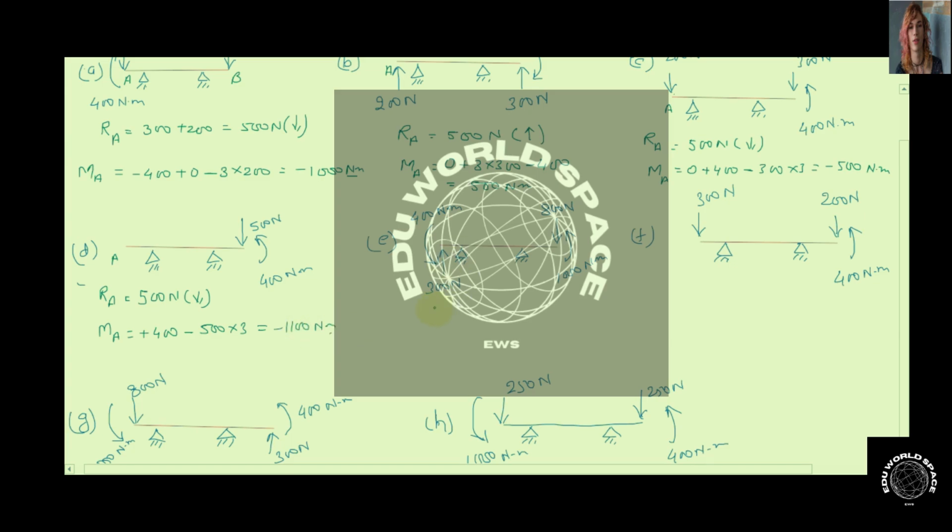Now if we talk about this case here, the reaction force at point A will be, since this 300 is acting upward, let's consider the upward direction to be negative, so minus 300, and this 800 is in the downward direction, so plus 800, which comes out to be 500 Newton. Since the final value is positive, our assumed direction, that is downward to be positive, is true. It means that the final reaction force or equivalent force will be in the downward direction.